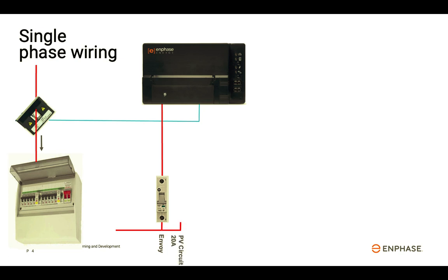Each solar circuit within an installation is protected with a 20 amp circuit breaker. If required, a 30 mA bidirectional Type A residual current device can also be installed in place of circuit breakers. The 20 amp Q relay is installed in line in the solar circuit. It will isolate the microinverter circuit if the AC grid is out of range.